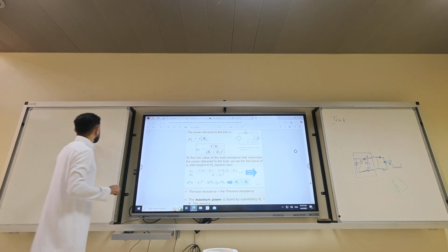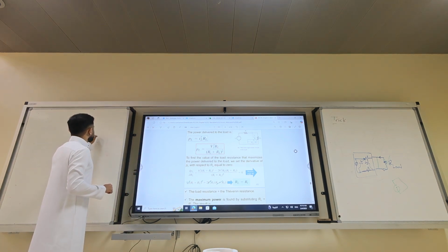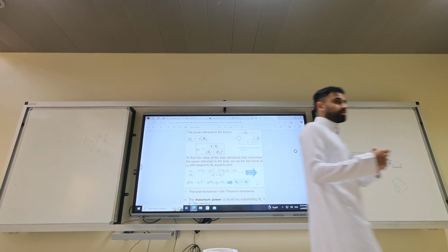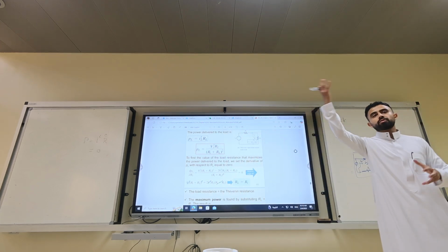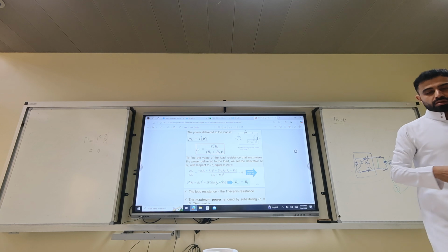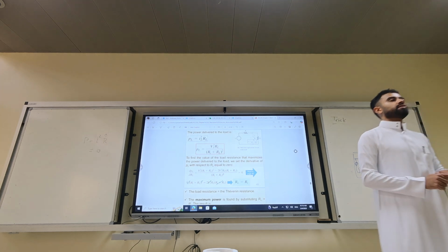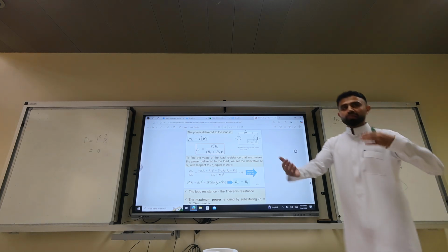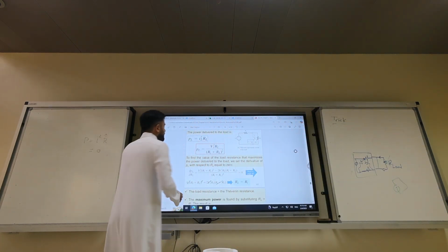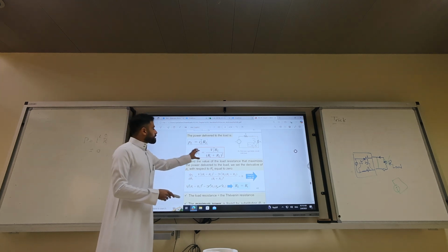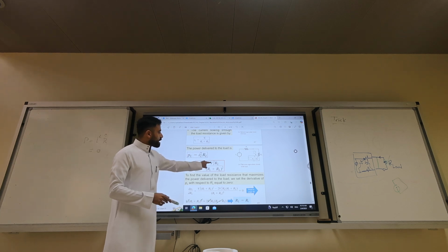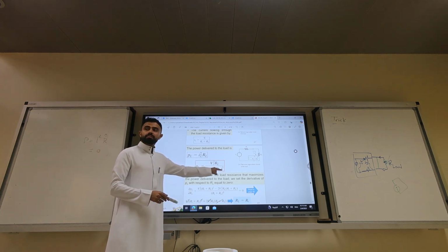So if you connect a short circuit, I squared times R, if the short circuit is 0, the power is 0. What's the power dissipated in a short circuit? Again, I squared times 0. What's the voltage drop across a short circuit? IR, I times 0. The math should work. Now, the power, if you substitute IL, Vt over, you will get Vt square over this term square.